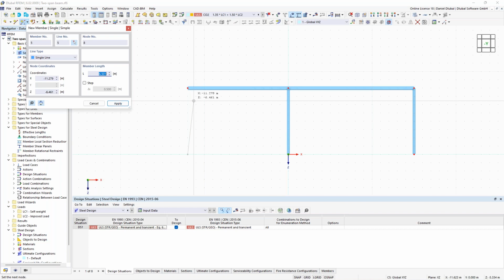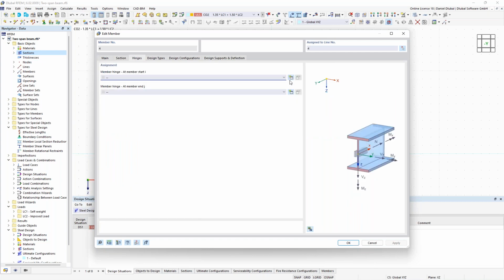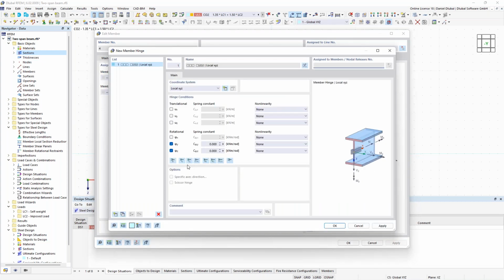And double click on that because I said it's a kind of truss. So on both ends we get hinges. I activate the option hinges and create new hinges. I activate here these moment hinges on both ends. I click OK. And now I copy this one, right click, say mirror it to the other side, create